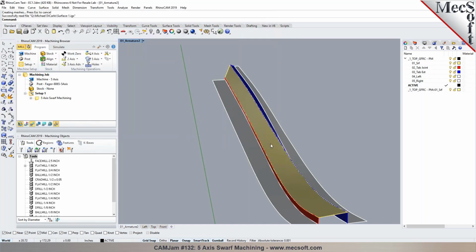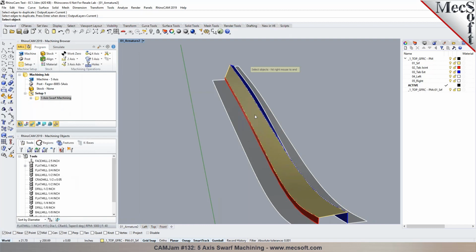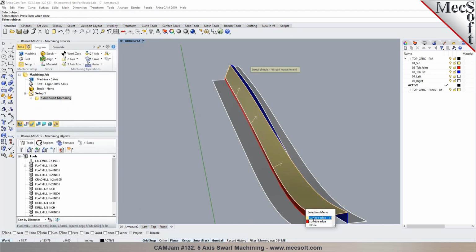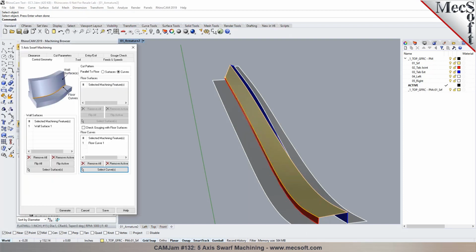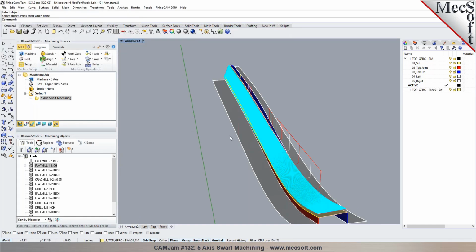You see now the surface is much smoother, nicer here. We can use that, and then I can go back in here. If you also want to do an edge creation, you can create a duplicate edge in Rhino and generate a sketch or curve from the edge. Now I can go back in here, reselect the surface, repick the curve, and generate the path. You'll notice that if there were any issues with the surface, now it's a lot smoother, right?